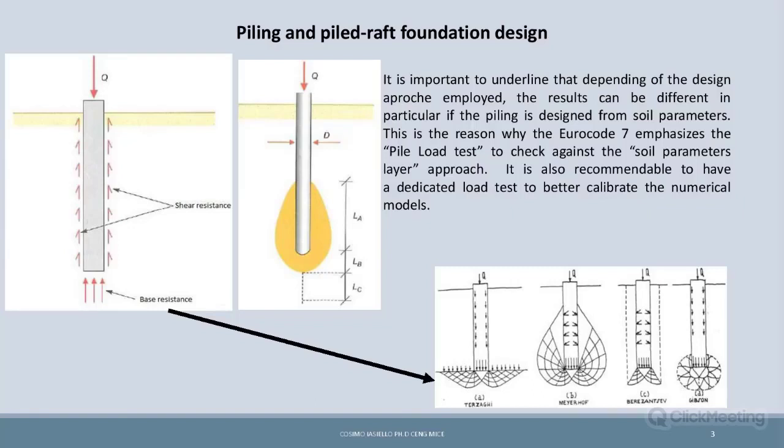The piling and the pile raft foundation is very easy. In our standards, the Eurocode, for people who are living in Europe, they clearly detect two ways of working of piling: piling which mainly works for shear resistance at the lateral skin friction, and piling working for base resistance.